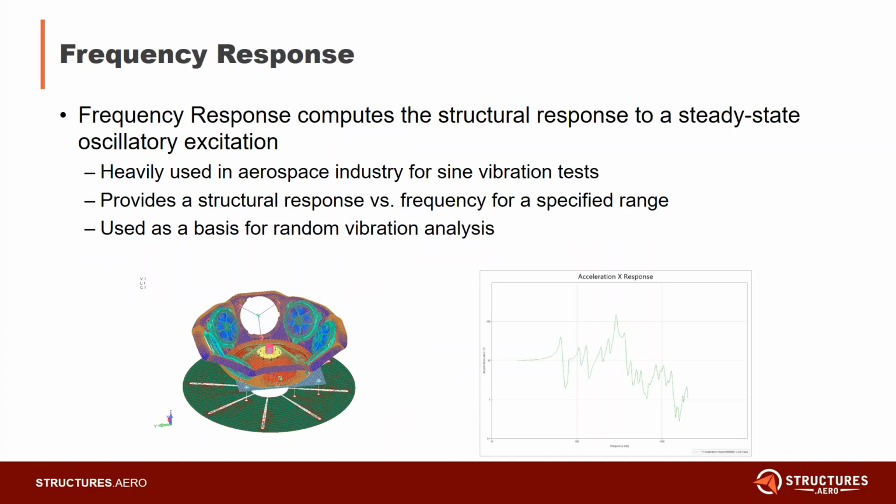Again, as mentioned earlier, it's heavily used in the aerospace industry for sine vibration tests. And what it will provide you is a structural response versus a frequency for a specified range. And we do have an example of some of the output that we'll be going into detail a little bit later. This frequency response is used as the basis for our following analysis, which will be random vibration, which takes this data and might use the transfer functions developed from a frequency response to determine your probabilities of different responses in the environment.